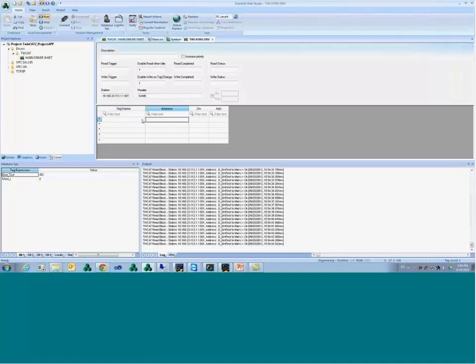All right, so I'm going to put here the same tags that we have, these 2 tags, and they're going to go to the same addresses. So we follow the same syntax. So it would be, for the global variable, just dot d underscore the int test, and for the local one, POU name dot the variable name.